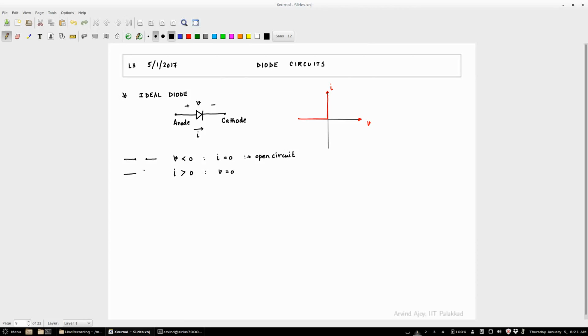So at the moment the voltage becomes, okay, forget about V equal to 0, I equal to 0. Forget about that situation. I think what you're asking is, what is the situation when V equals 0? Right? Forget about that, because in a real diode that is not really going to happen. So as long as V is infinitesimally greater than 0, basically you have shorted the input and the output. So whatever the external circuit requires, that amount of current will flow. Okay. Forget about the singularity of the transition region. Okay. All right.